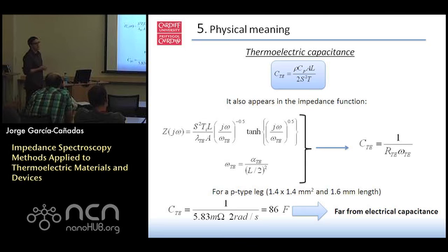So this thermoelectric capacitance also appears in the impedance function. This is the equation for the thermoelement of the impedance. We have our characteristic frequency, so the thermoelectric capacitance can be worked out using these two parameters.